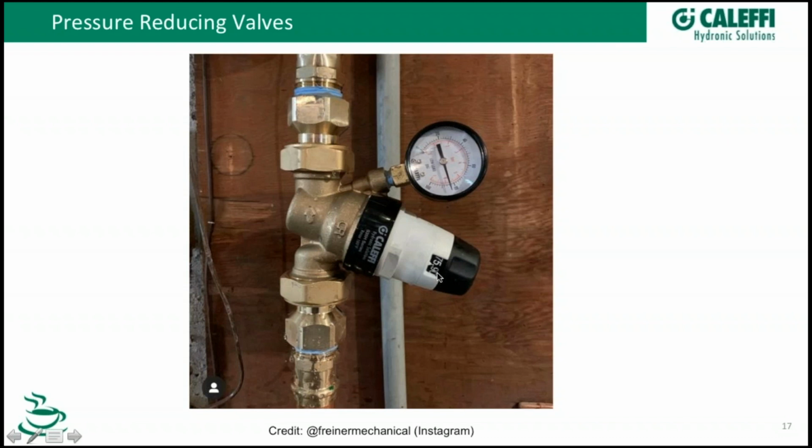On the knob or the setting window, it's between about 75 and 90. And if you got your really good glasses on, you can see the gauge is right about 80 PSI. So he's probably still adjusting that a little bit, but it's a great way to get it done, and it's a lot less cumbersome versus the couple of wrenches and trying to loosen up that jam nut and having a gauge somewhere down the line. This is also a great slide to point out the fact that he's got adapters on there, going from our female NPT to press connections. It's likely that this is probably just what the wholesaler had in stock, but just remember that we offer these in press connections as well.